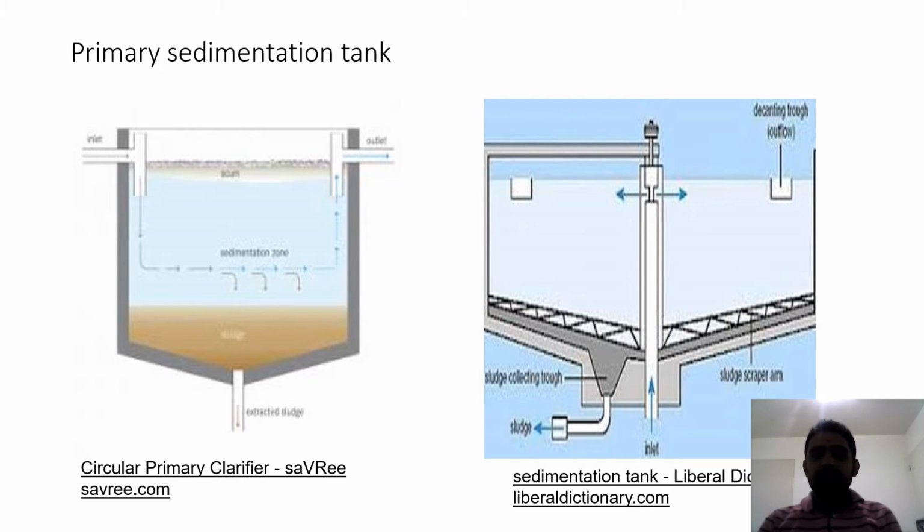The figure shows the primary sedimentation tank. The water treated in the primary treatment with the chemicals enters this tank, and the flocks which are generated are known as chemical sludge. It settles at the bottom, brown in color, and this sludge can be removed by various means, and the clearer water from the surface goes to the next treatment, like the aerobic treatment.